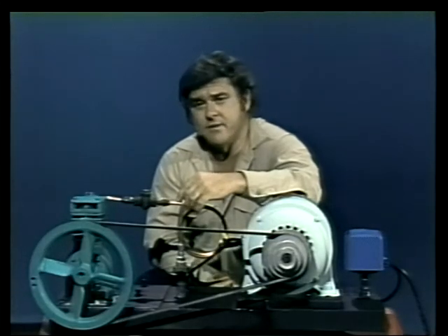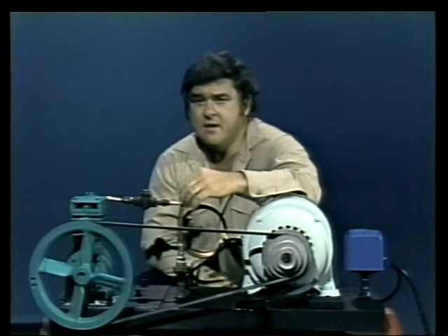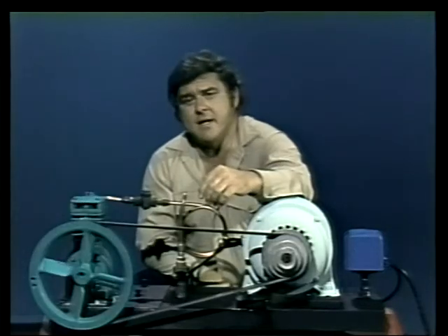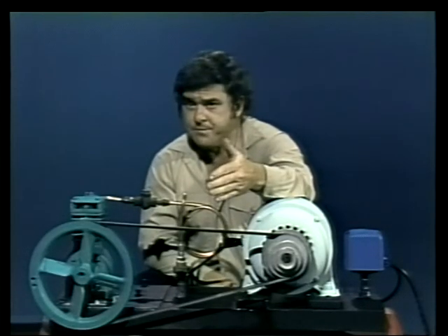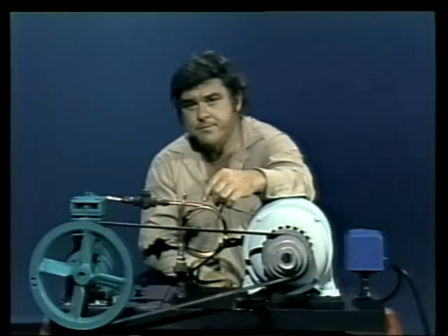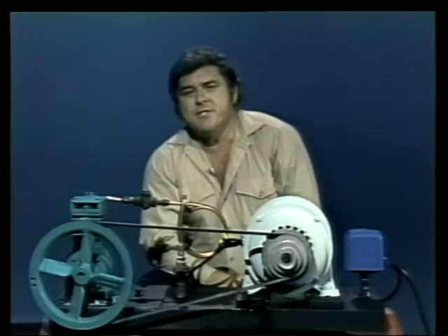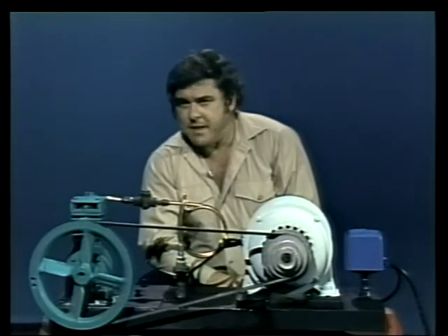Inlet valve throttles on dynamic compressors are typically called into play only when there's a major leak in the system it supplies. For example, if an airline burst, the sudden increase in demand would cause the valve to close down. In an extreme case like this, the compressor would be completely shut down until the piping was repaired. Normally, though, pressure isn't allowed to get high enough to burst a pipe.